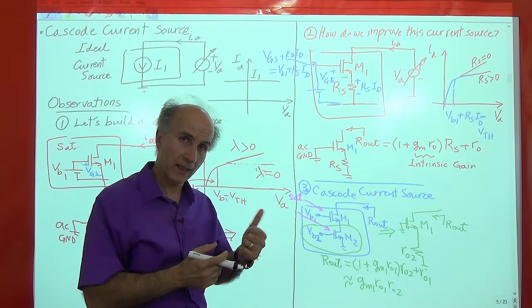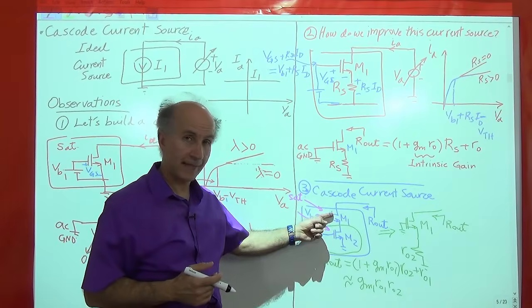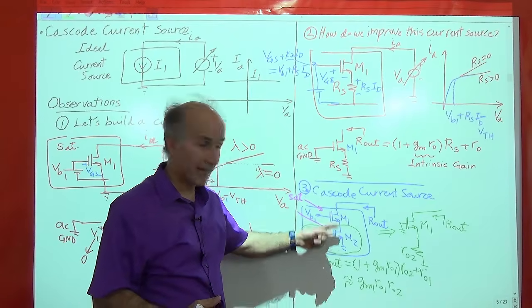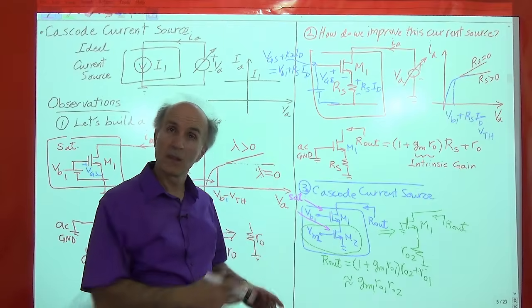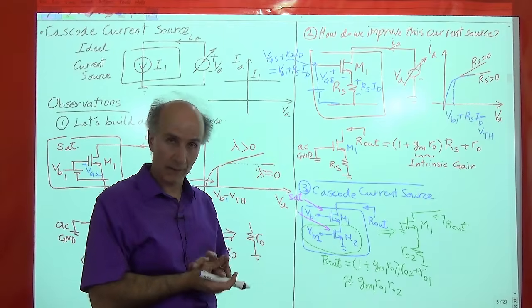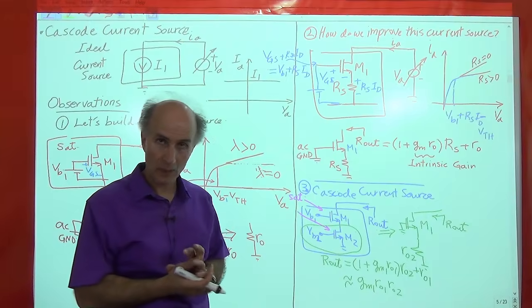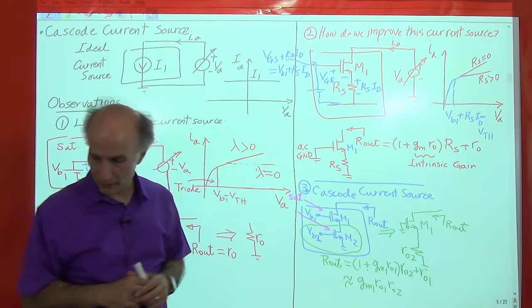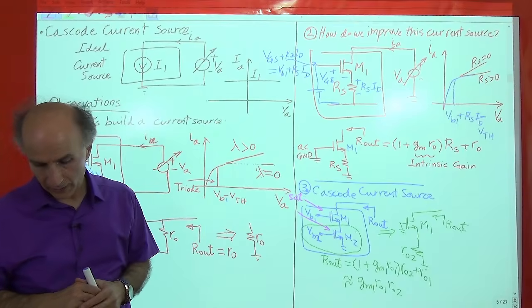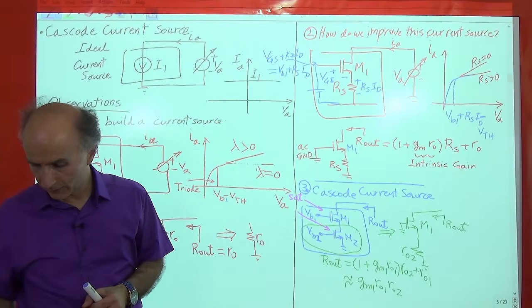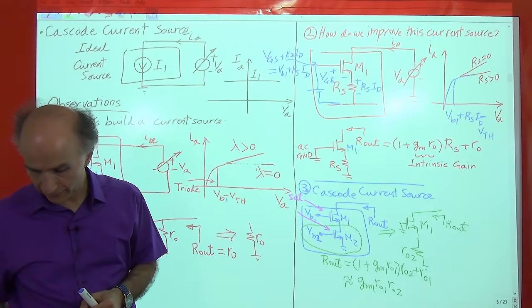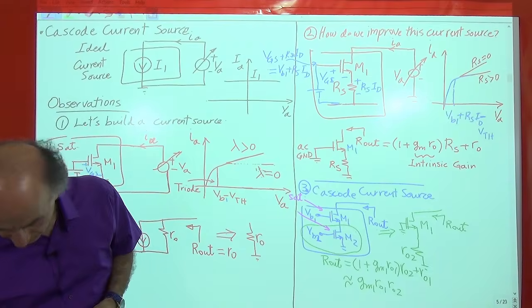So in one case, we say M1 is added on top of M2. In the other case, we say M2 is added below M1, right? Even though it's really the same circuit and the same function. Okay, so this is the basic structure that we have for the Cascode. And let me make sure that we have covered everything that we wanted to say. All right.